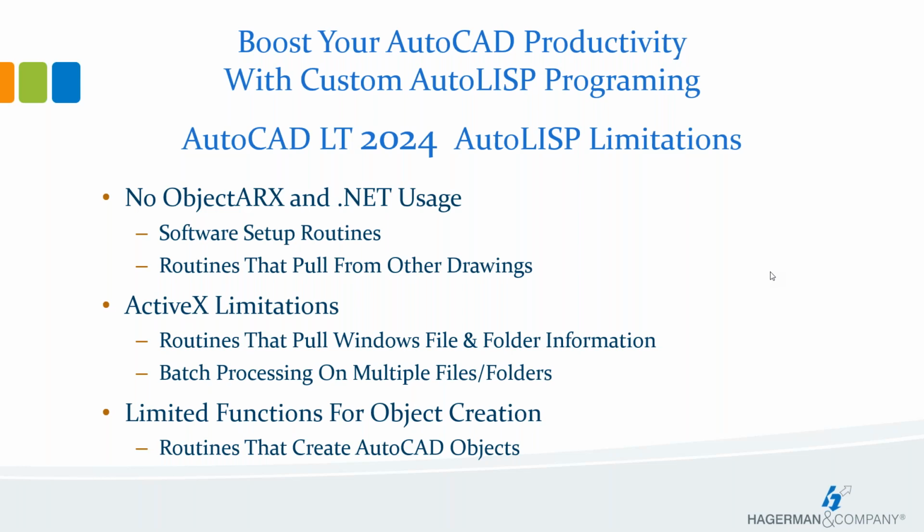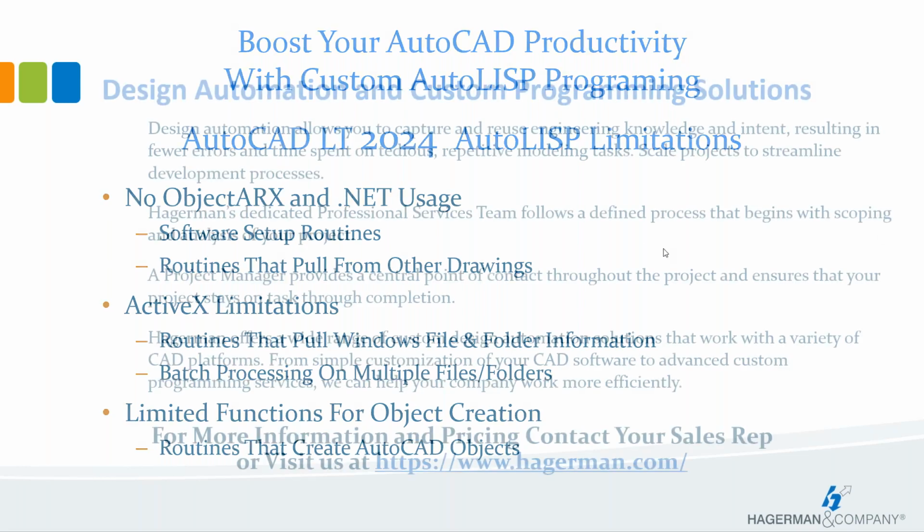There's also limited functions for object creation, and this is not talking about drawing a line and stuff like that or inserting a block. This is talking about routines. I've done routines in the past that literally create objects, blocks and stuff like that with attributes, and everything's created on the fly through the object. A lot of people do stuff like that, and routines that create AutoCAD objects will not work in LT.